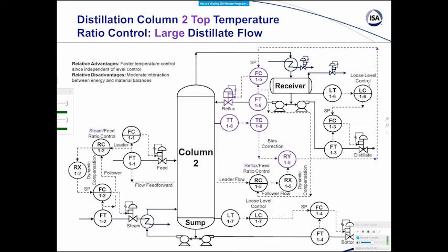You've got to be careful, though, that if you just decrease the level controller gain, you're going to most likely get into very slow oscillations, and that's not good at all. And that occurs often, we'll see, for temperature control systems. You just don't want to decrease the level controller gain. You get into oscillation unless you've greatly increased the reset time.